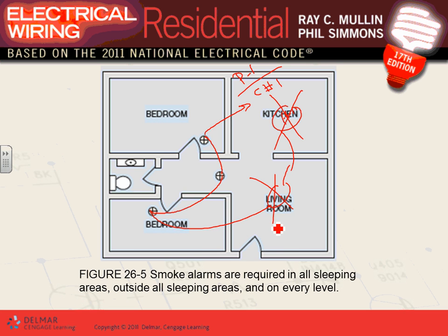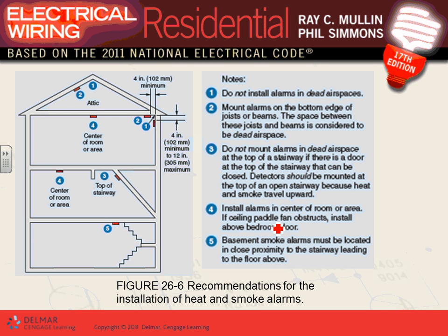Sleeping area, every level, every area adjacent to sleeping area. Okay, location. Now we know where we need to install them. How to install them in this area? There are a few areas, guys, where you do not install. They don't want you to install them in corners. Can you guys see this area here and this area here? The reason why they don't want people to put them here is that by the time the smoke reached that corner, the whole room will be engulfed in fire. So they don't want you to put them in those areas. Here are all the locations for them.